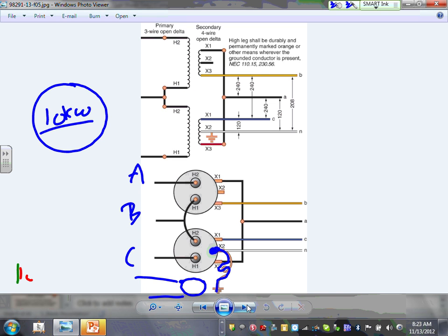By the way, I can deliver 10 kW using DC to your building, DC voltage or AC voltage, single phase or three phase, any voltage system. The key point is the 10 kW. How do you deliver it? You choose the best delivery method for the application. This delivery method is good for utilities because it saves them one transformer here, right?